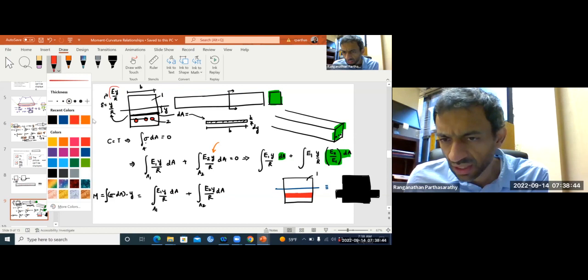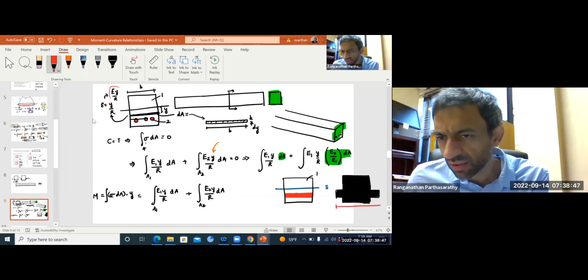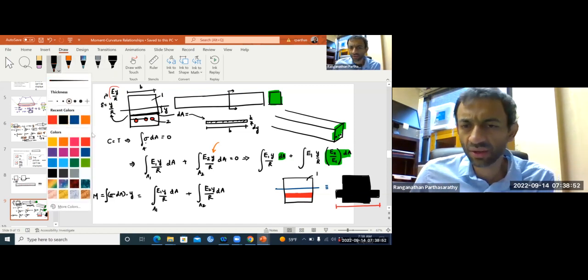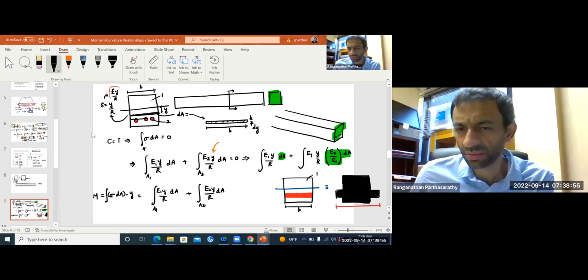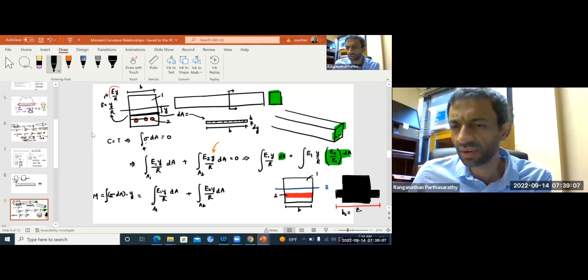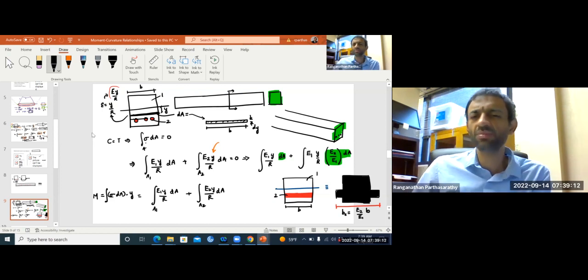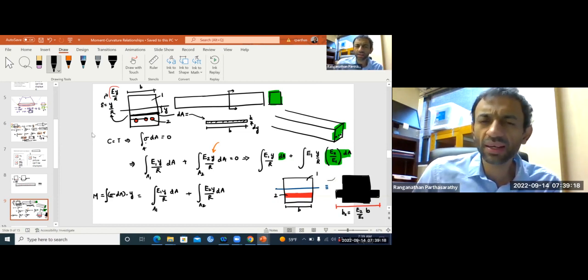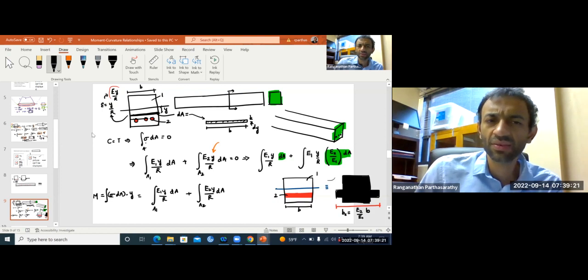Just at the level of this steel, now this equivalent rectangle here is not of the same width as in the original beam. So in the original beam, if the width was B, here my equivalent B is going to be, this is material 1, this is material 2, E2 by E1, that's the modulus of 2 by modulus of 1 times B. So I'm stretching this out. Why am I stretching this out? Because I want at every level everything to be the same material, right?